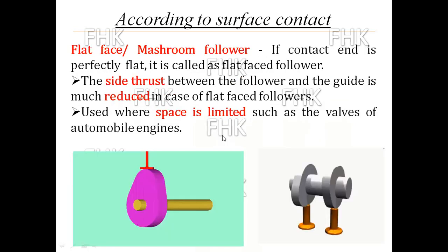Now, the third type of follower is flat face or mushroom follower. If the contact end is perfectly flat, it is called a flat face follower. The side thrust between the follower and the guide is much reduced in case of flat face follower. This follower is used when space is limited, such as the valves of automobile engines.